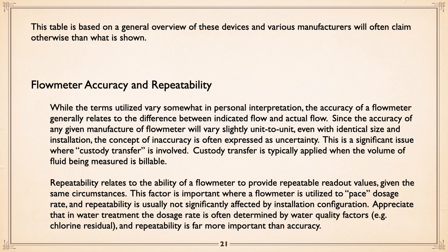You want accuracy. In other words, if you've got a flow meter, and most of these will total by themselves, by the way, but you can total within a PLC. Basically, I want to move 30,000 gallons from this to that truck. Okay, fine. You're measuring flow, so there is where accuracy is important.